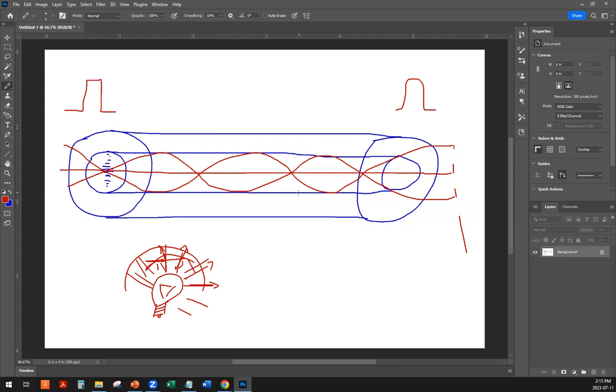Okay, and then those are further away than 300 feet from the MDF, which stands for main distribution frame. So then the whole thing is converted into fiber optic, into the optical signals, through something that's called a media converter, and that is connected with the fiber optic. Usually it's about 500 meters, no longer than that, but you can probably go more.